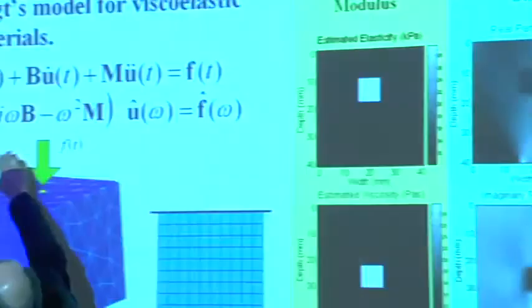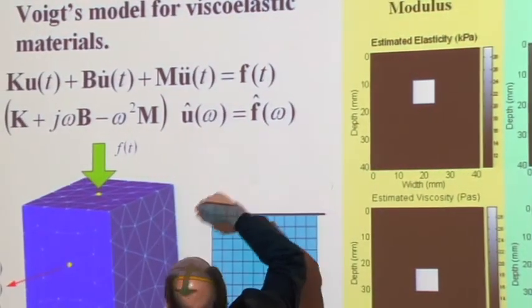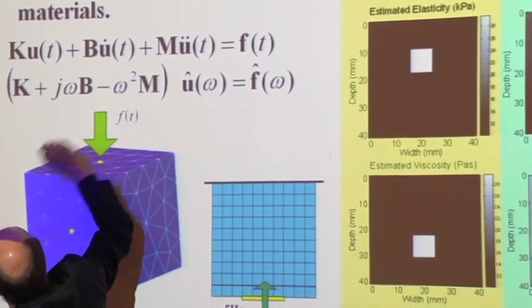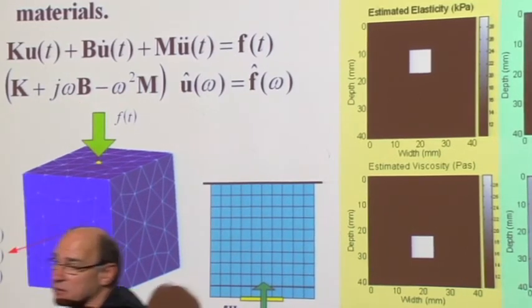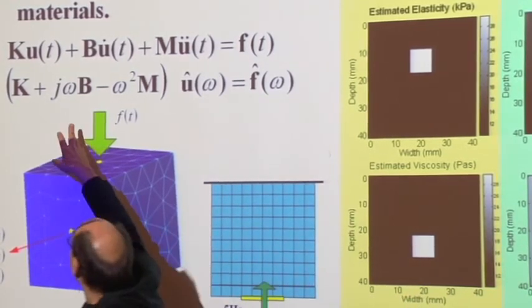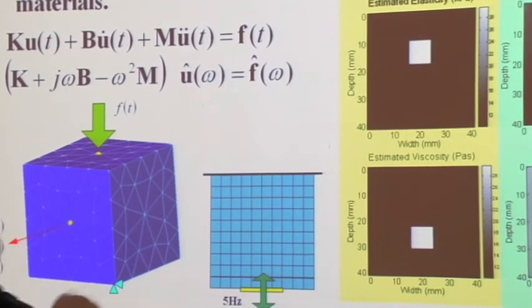So we're trying to invert this. You know what omega is. Let's say we know the force, it doesn't matter. What you want here is, if we know M, we want B and K. So you have a number of parameters. For each unknown parameter, you know from system identification, a linear system will require typically one spectral line for every two parameters, because you have the sine and the cosine, which each give you an equation you can solve for the two parameters.